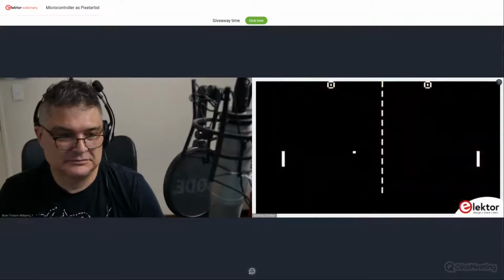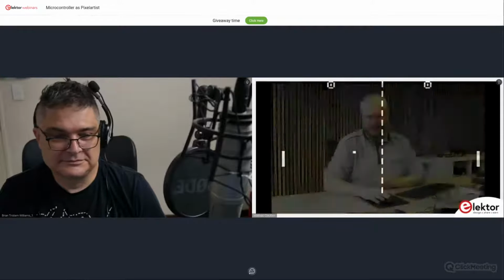Yeah, I said circuitry and some more hints on the AVR and video output you can find in the article. There's a lot more going on. Also, some guys managed, with a lot more trickery, to get PAL color output. But that's a different story and not for today. And yeah, I think that's that. If you want to give your kids something to do, a little bit of Pong, a little bit of Space Invaders, it's not many parts that you need, just the AVR, a few resistors, a few buttons, and you're good to go. Ready is your game system.